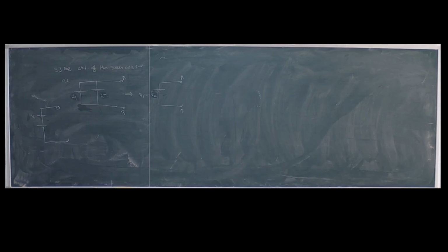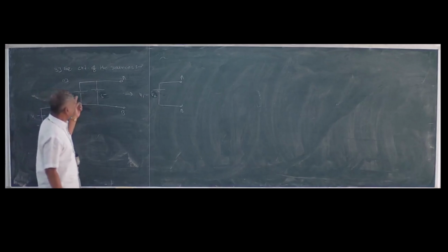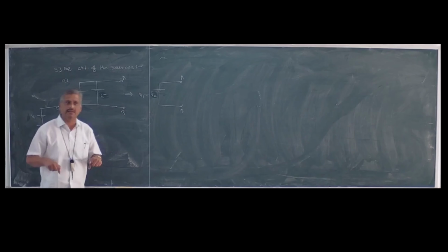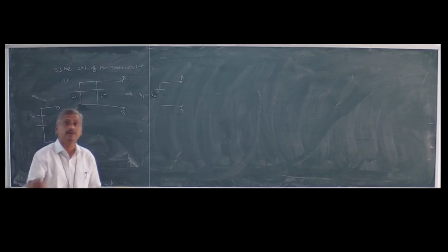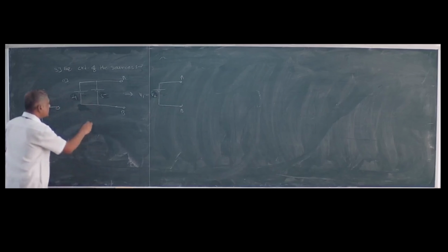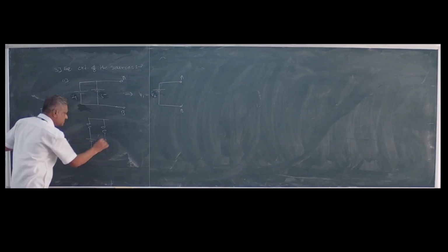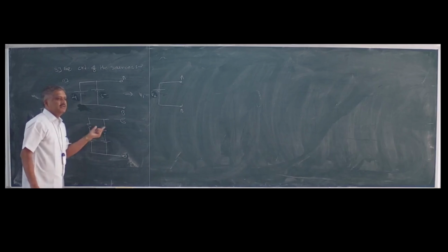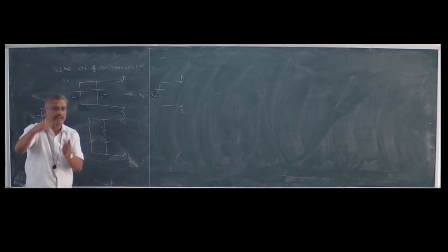And they have given which circuit is invalid. When we are connecting different sources in parallel without any internal resistance, such sources cannot be connected. If we connect them, it will burn one of the sources. We can connect the two sources in parallel in this fashion. That is allowed. This is one and this is the other. It is allowed because some voltage drop will be there, because the potential across the parallel element must be the same.